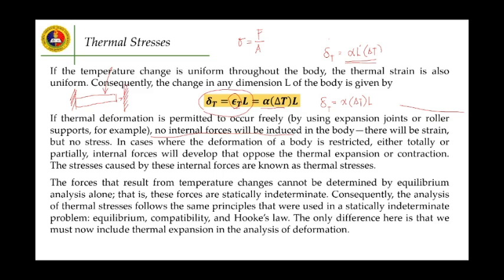Consequently, the analysis of thermal stresses follows the same principles that were used in statically indeterminate problems, which are equilibrium, compatibility, and then Hooke's law. The only difference here is that we must now include thermal expansion in the analysis of the deformation. So basically the same thing.